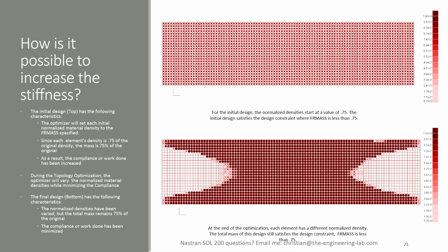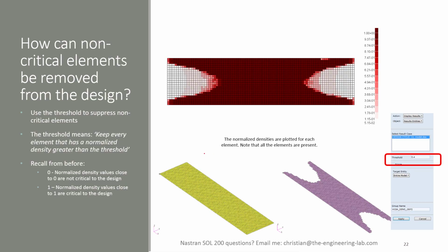So here as an example, you can see the spheres are smaller than the squares. This is a reduced version. This is where your optimization starts from. And then you can imagine that the optimizer will size the normalized densities so you can determine based on these ranks, if you will, which elements should remain in the model and so on.